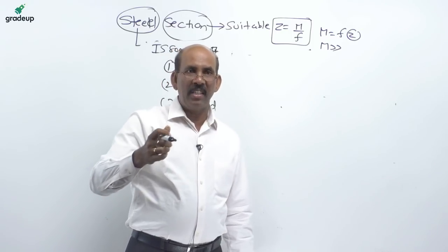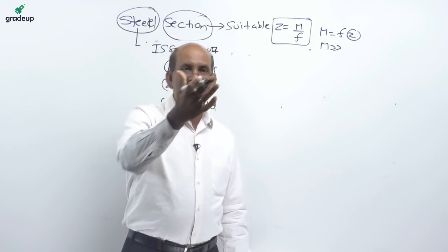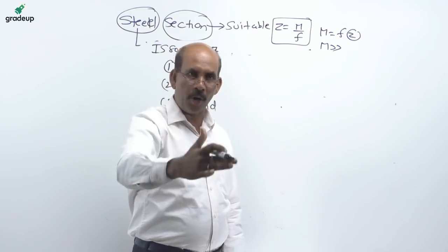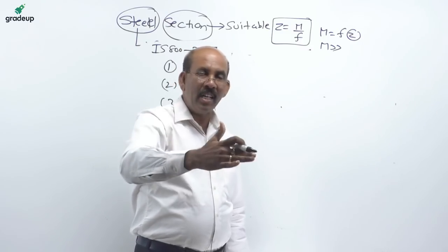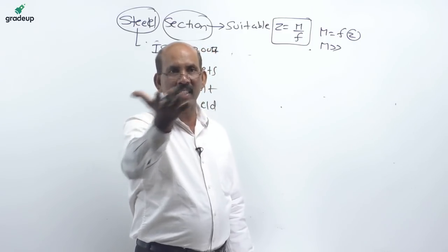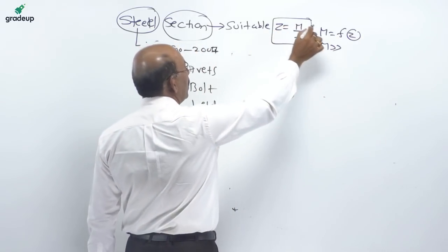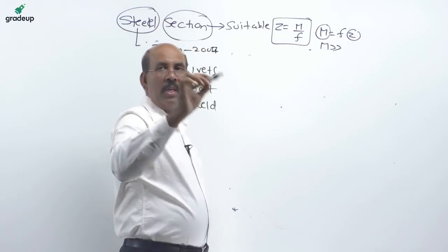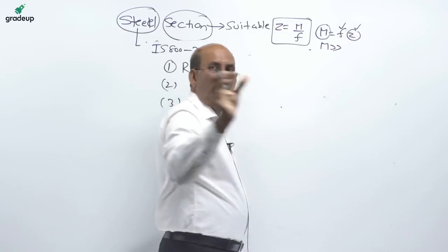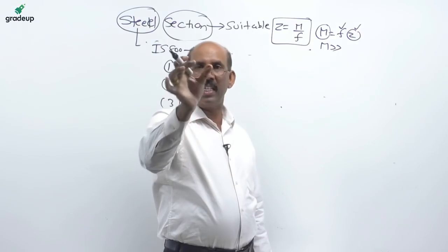Mr. Venkateshan, it is a very good question. Strength of section is only defined for moment. It is nothing but strength, as I told you, resistance against the load. Load causes bending, and bending produces the bending moment. Against the bending moment, the resistance is nothing but the strength of the section. So here the strength of the section is nothing but the M value, the moment of resistance. Again, it depends upon the stress and the size or the shape of the member. So as I mentioned, the I section is very effective. That is the only reason.